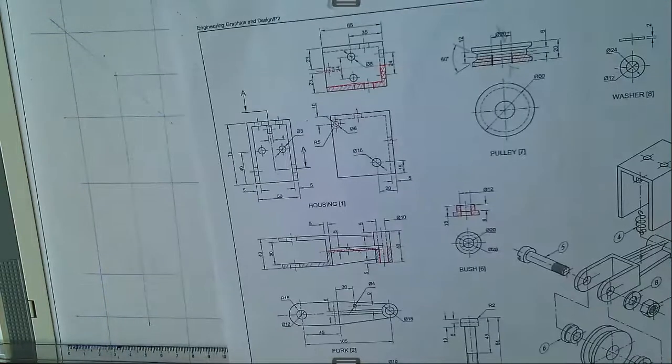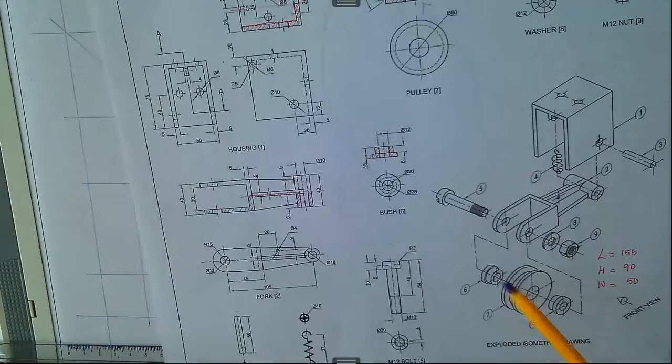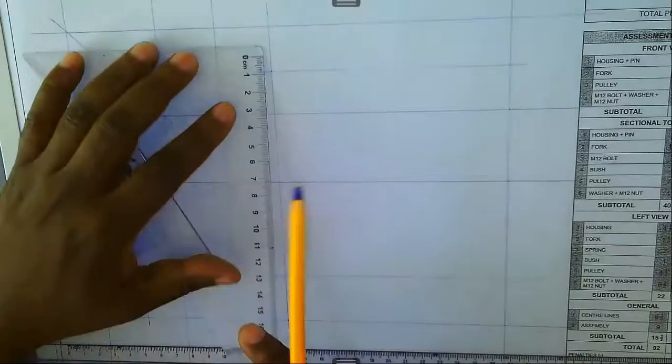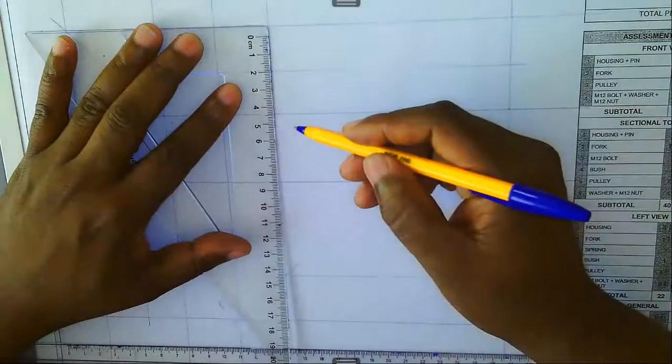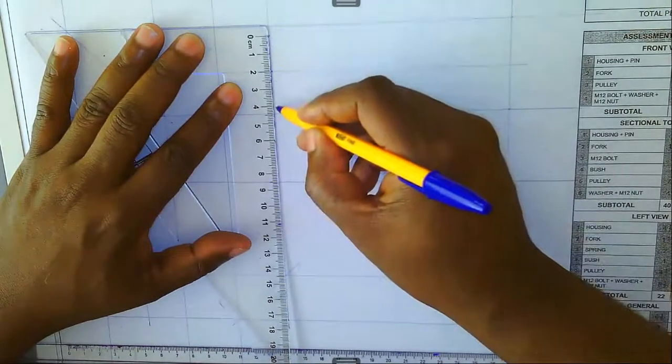Now we know that the washer is secured to the fork, as well as the bolt is also in contact with the fork. And the fork is in contact with the bush as well as the other bush on the other side. So what is the size of the fork? In terms of the width, it's 40. So either side, we need to measure 20 and 20 so that we know where to position our washer. So we have got this, and we have got that as well.